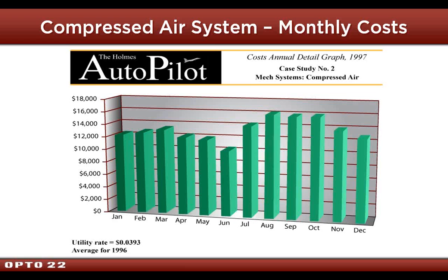This was the GE plant in Louisville. They had 15,000 horsepower of air compressors scattered over 1,100 acres in 5 different buildings. So we had to hardwire and run our RS-485 cable to hook all the different Opto panels together. But once we got all the data on one screen showing CFM from every compressor, every location, we showed pressures, we showed energy use of each of the compressors. By looking at them individually, they'd done the best they could to tune them. But by seeing it all together, our reports showed system efficiency.